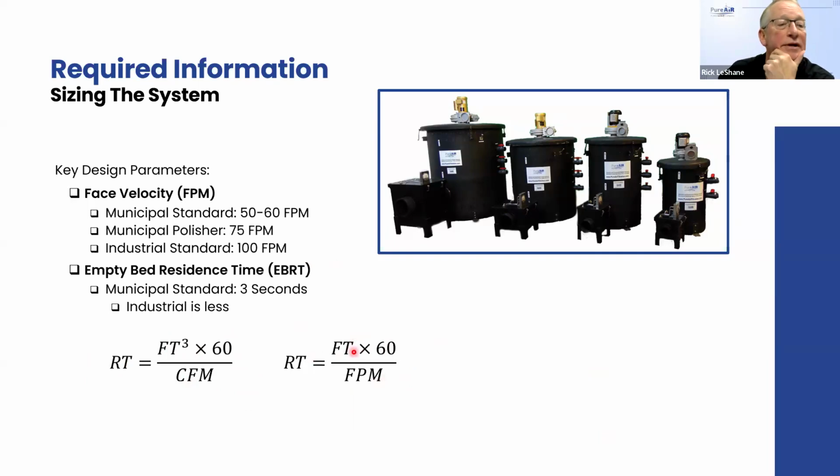We know the depth of the media bed, which most of the time is 3 feet in the wastewater world. Times that by 60, and that'll give us our residence time. So again, just other tools or formulas that we use to help us size the systems. Let's go to the next slide.